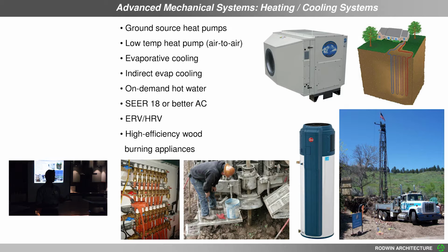On the on-demand hot water, does that, in terms of how much water it uses before the hot water comes out of your faucet? Yeah. I was under the impression that the on-demand hot water ones actually use a little more water than what you've got. So I've got a better solution than that. Very inexpensively, you can install what's called a recirculation pump.